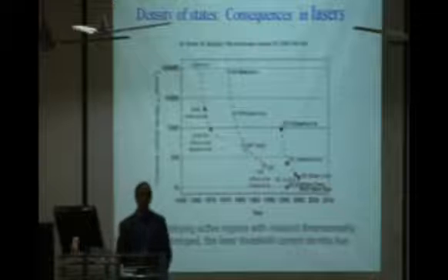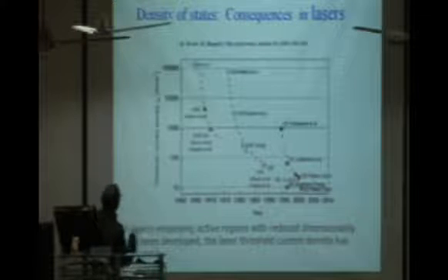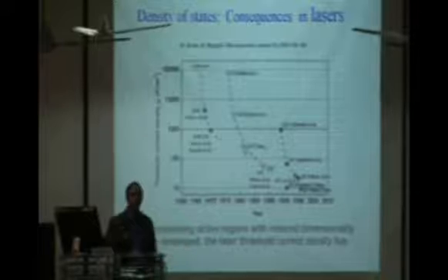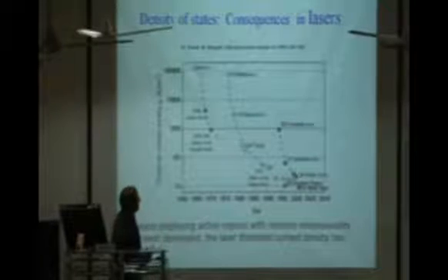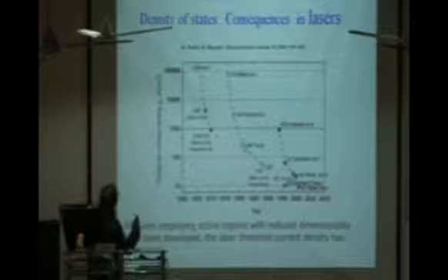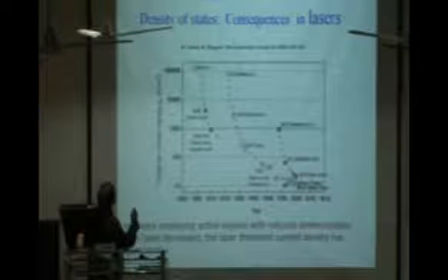We can put a similar roadmap for an optical system. In a laser, the most important figure of merit, or parameter, is the threshold current density. That means how much power I have to put in this laser so that I can get this lasing action to take place for the whole day or for the whole duration of the conference. And you see, it initially starts with a typical gallium arsenide PN junction of about a million ampere per centimeter square.